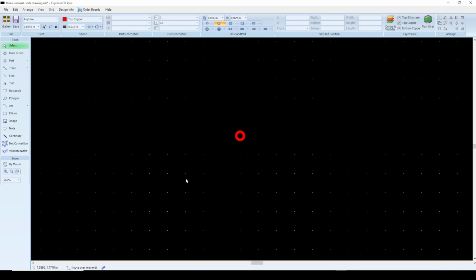Oh, and one more thing. If you place an item with the snap turned off, and then you turn the snap on, the next time you move that unsnapped entity, it will indeed snap to whatever snap setting you have selected. So it does not remain in a condition where it's not snapping to anything. It will just start snapping to your grid.